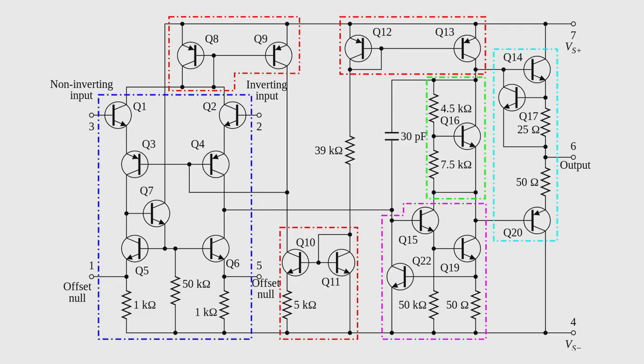Along with all the interconnecting resistors. And you'll notice, for capacitors, there's only that one 30 picofarad capacitor. The signal comes in on the left-hand side at the input. It never goes through a capacitor. That means you can put in a DC voltage at the input and get a DC voltage at the output. It can amplify AC or DC. And that one capacitor in there is a compensation condenser. The signal doesn't actually have to pass through it. I thought that was quite interesting. Yeah, it's pretty cool stuff.